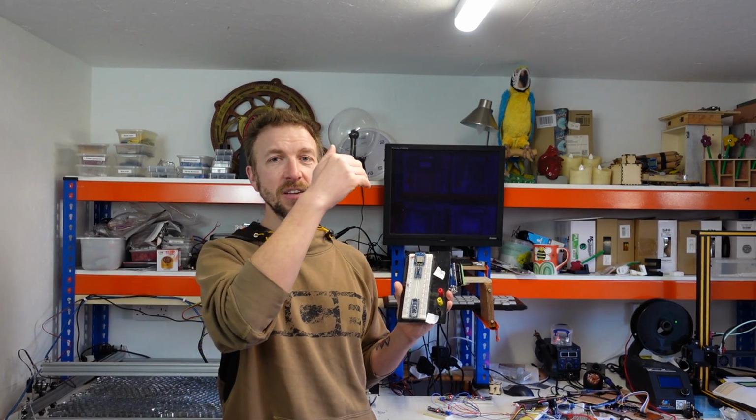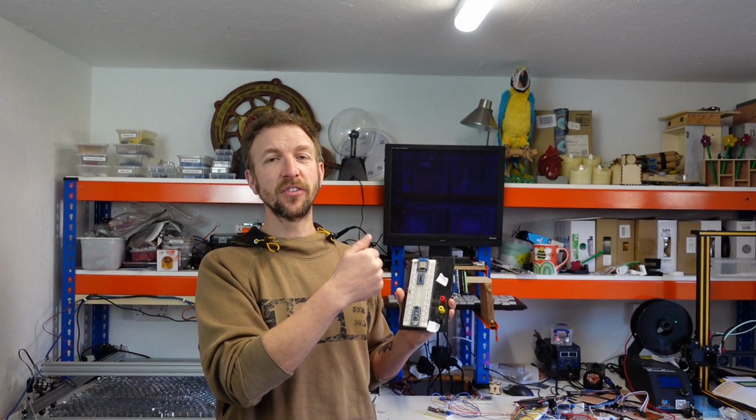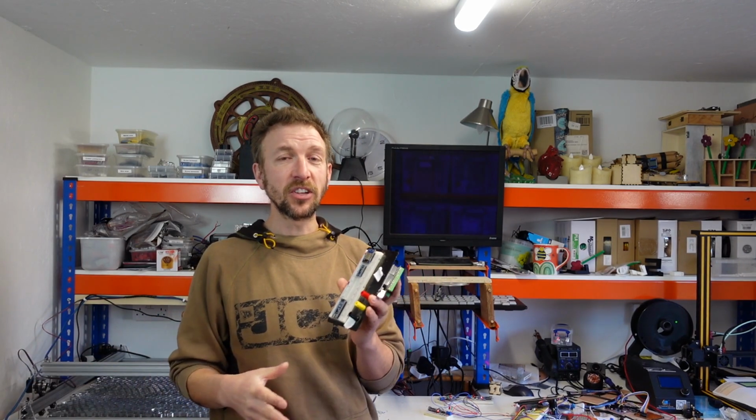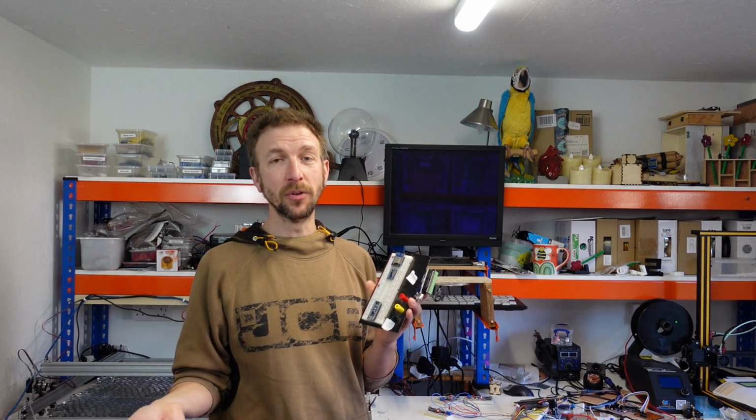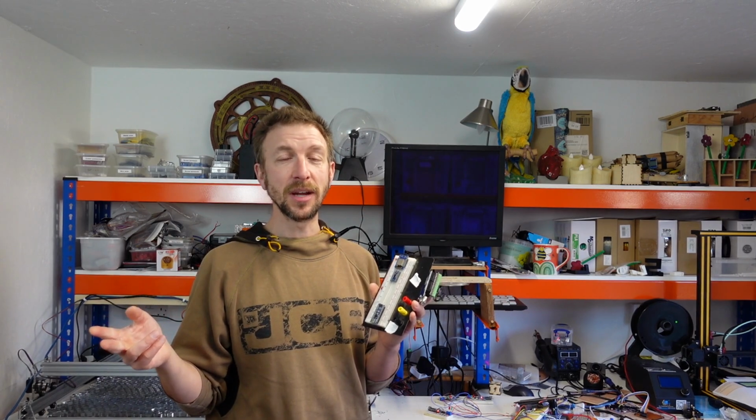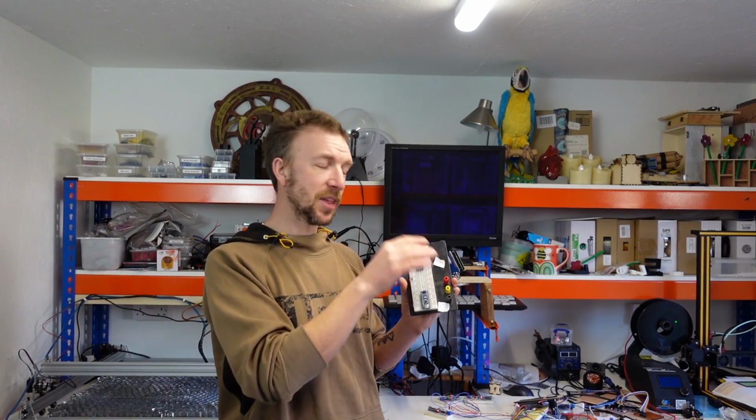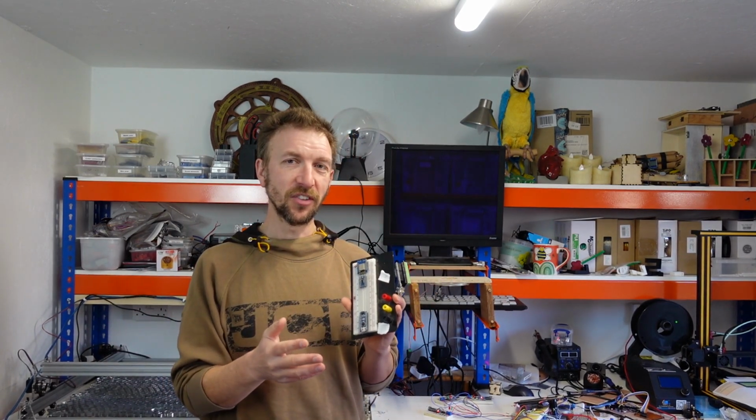So connect the transmit and the receive lines of one of the serial ports on the ESP to the Arduino serial transmit and receive lines. The ESP itself has actually got 3 UART ports, but it's got 2 that are easily available anyway. So I can still do that without disturbing the serial receive functions, things like that.